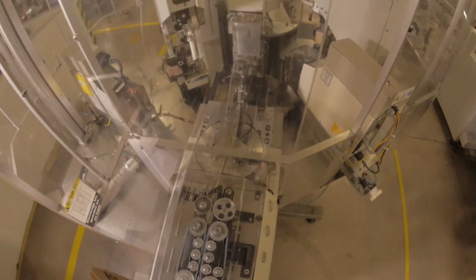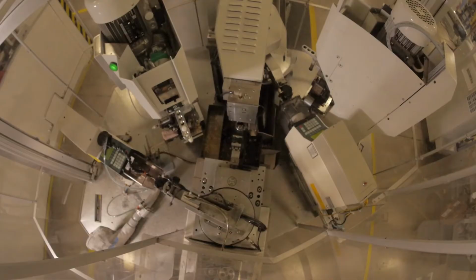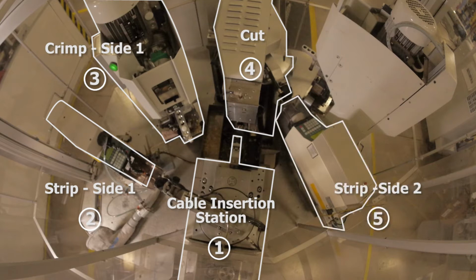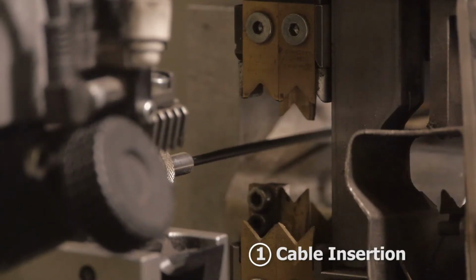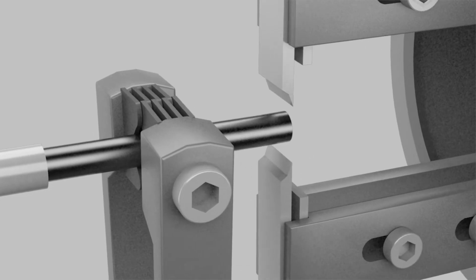The cutting equipment has 6 stations to perform the following function. 1. Cable insertion station. 2. Strip side 1. 3. Crimp side 1. 4. Cut. 5. Strip side 2. 6. Crimp side 2. During production, the cable is cut in one end to start the process. The stripping station removes the dielectric and the outer jacket to length per equipment settings on one end of the cable.